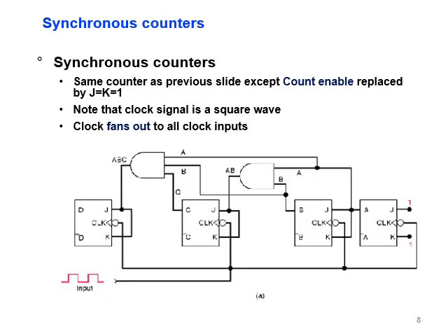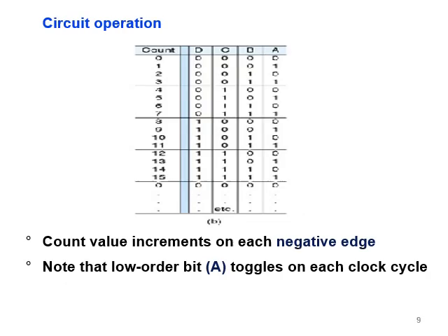Now, this is another shape for the same previous discussion. Just here, we entered 1 as input here and here, as you can see. Otherwise, this is 3 digits. This is the first one, second one, no, 4, sorry, 4 digits. And it's the same principle, the same working. J and K equal 1, not 0. So the way of operation of the circuit, it will be counting with an increment. You see, 0, 0, 0, 0 for the first state, 0, 0, 0, 1, 0, 0, 1, 0, 0, 0, 1, 1, 0, 1, 0, 0, and so on. Counting, adding more numbers to increase the counting.